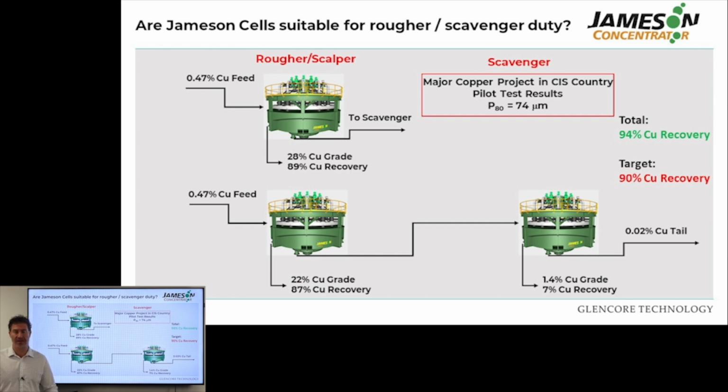We added an extra 7% copper recovery, so all up, 94% copper recovery. That was well above the target recovery defined by the client. Also, for your information, there was parallel test work with mechanical cells, and we matched the same recovery with only two stages of Jameson Cell flotation.